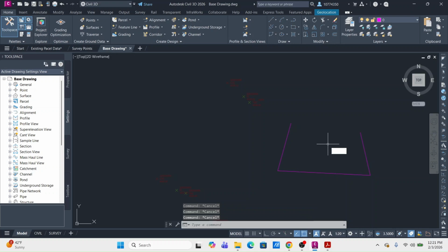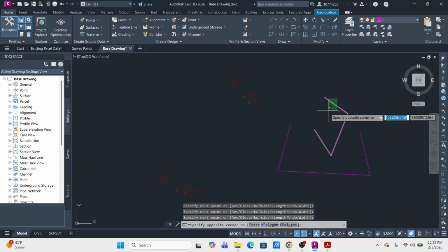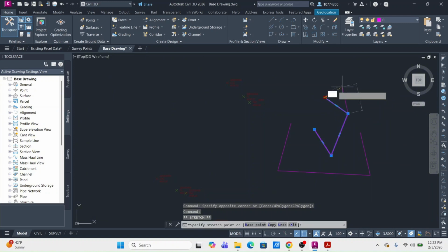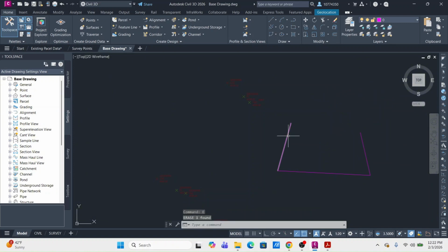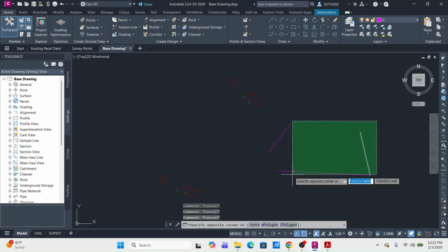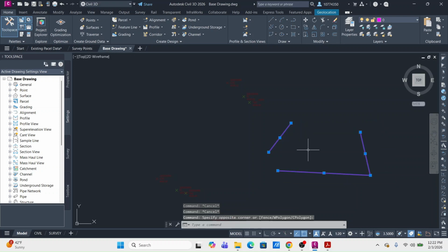Compared to a polyline, if I go like this, it becomes one singular object, one that I can manipulate and move around and do just about whatever I want with. If I were to move these endpoints on the lines, each moves as its own object, and we don't want that. We just want one continuous line that has different points for editing purposes.